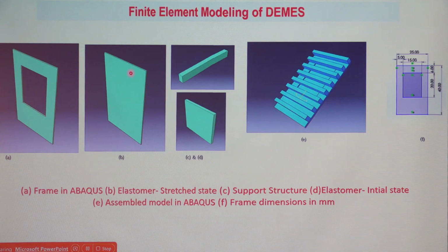The membrane is pre-stretched, then you attach the frame. Experimentally you also do the same thing. In a separate simulation we find the principal stresses, and in the second simulation provide the entire membrane these principal stresses as an initial condition. Then do the assembling, and repeat the same step.